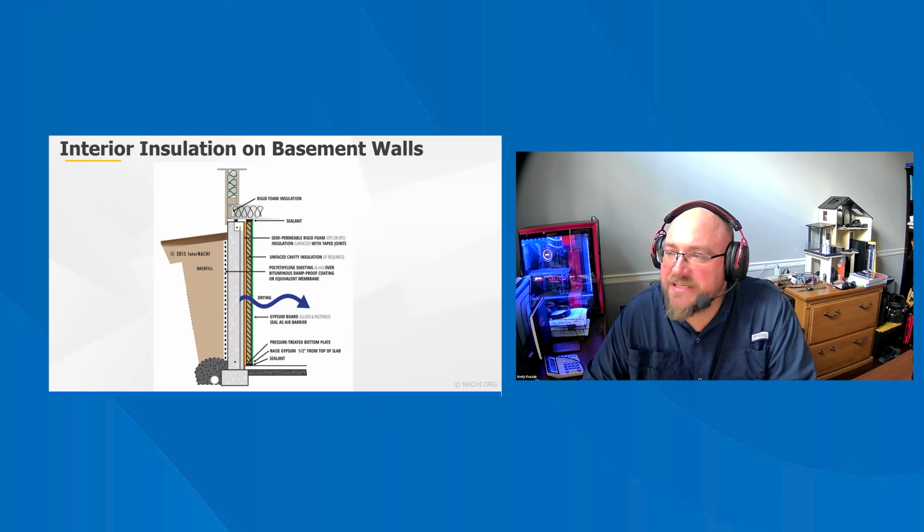Humid air at the basement's interior should be prevented from leaking into the finished basement wall assembly and subsequently condensing. The interior side of the wall assembly should not have large holes in it. The ideal approach uses the gypsum wallboard as an air barrier and requires sealing any penetrations through and leaks around the panels. Air sealing of ceiling penetrations in the basement should also be addressed.